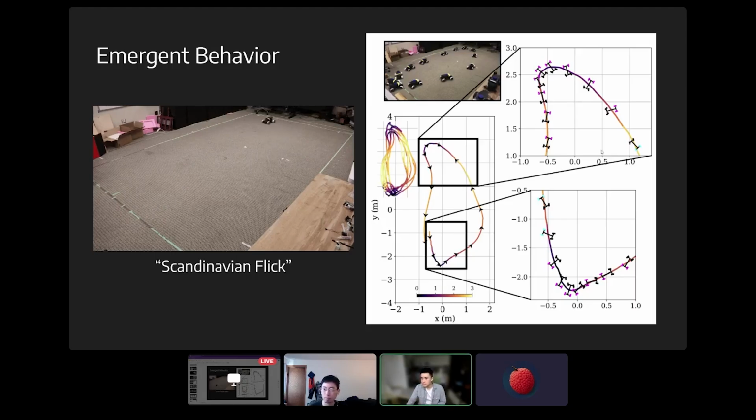If you zoom into one of the turns here, you can see that we visualize that the robot has a certain steering angle and a certain throttle command. So blue indicates cold wheels or no throttle, and pink indicates hot wheels, which is high throttle. As we're coming to this turn, the robot is speeding up, and then as it gets closer to the turn, it cuts its throttle. The wheels go cold, and you can also see that as it goes in, it's kind of wobbling.